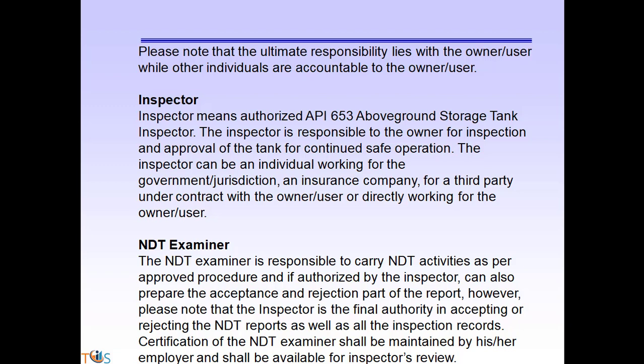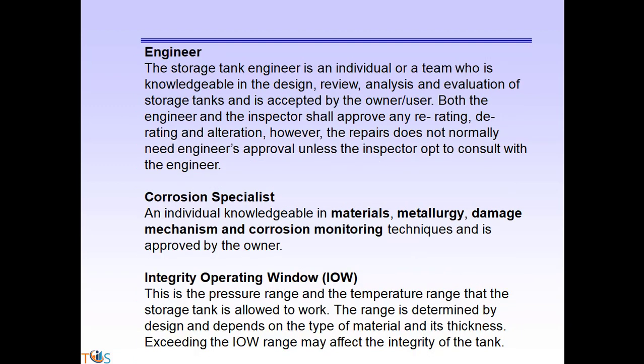NDE examiner. The NDE examiner is responsible to carry out NDE activities as per approved procedure, and if authorized by the inspector, can also prepare the acceptance and rejection part of the report. However, please note that the inspector is the final authority in accepting or rejecting the NDE reports as well as the inspection reports. Certification of the NDE examiner shall be maintained by her employer and shall be available for the inspector's review.